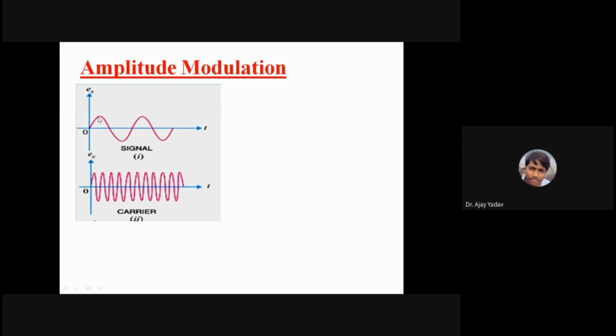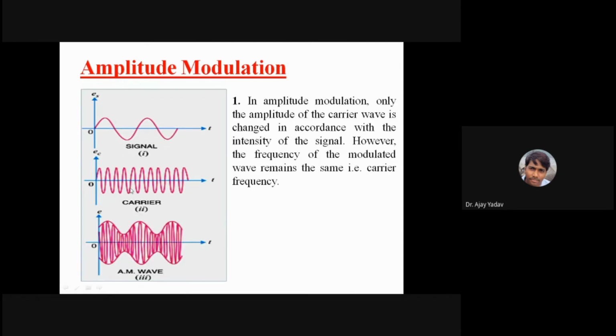Now here if you see, can you see the mouse pointer which I am moving around here? The data signal. Yes, sir. Okay. Now here the data signal amplitude is high. So in the resultant signal, the carrier wave amplitude should become high here. Now your data signal amplitude is minimum. It goes on the negative cycle, negative maximum. So here your resultant signal amplitude should become minimum. Here again maximum, minimum. So the resultant wave will look like this.